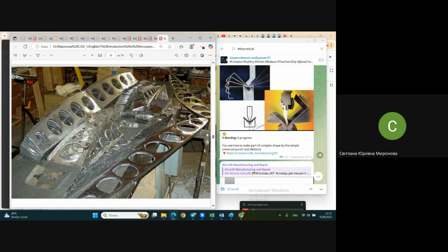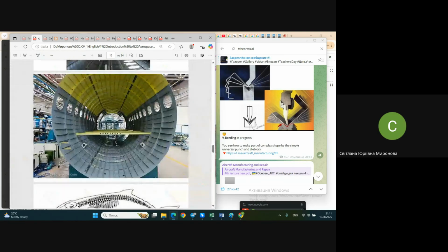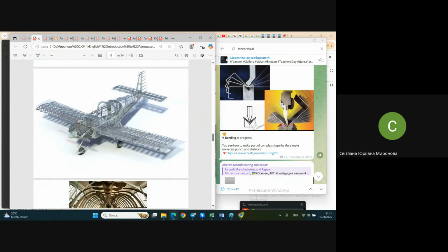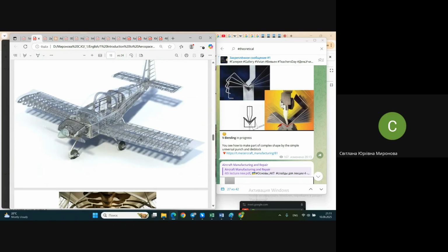Do imagine the wing. I remind you what it looks like. Even a simple airplane, how many ribs does it have? And it's a straight wing. It means that all the ribs may be of the same size and may be produced by the same couple of punch and die block. Do remember this: if we need to produce something by sheet metal stamping, this something demands a punch and die block. Any change in size, design, shape, another couple, punch and die block, another spending of money.